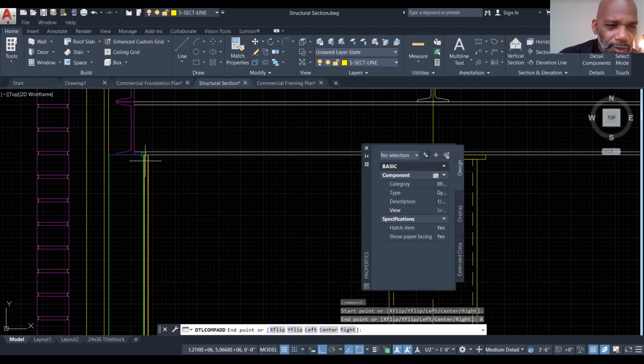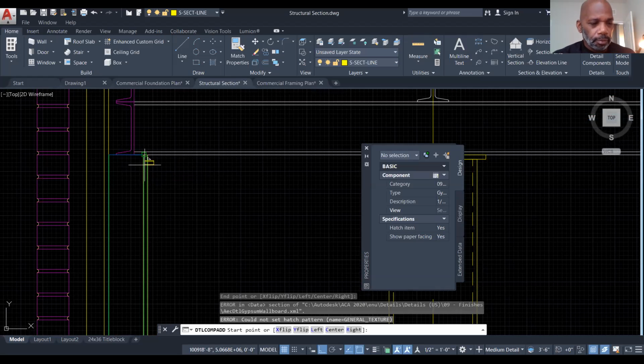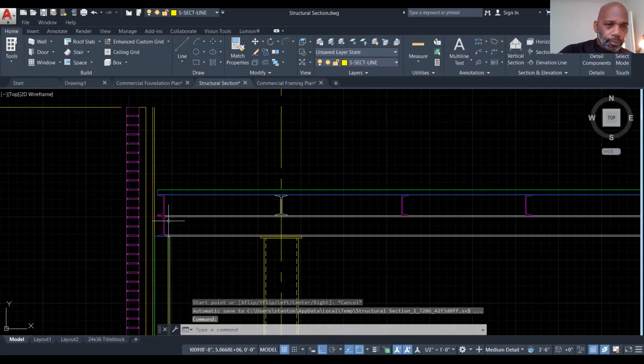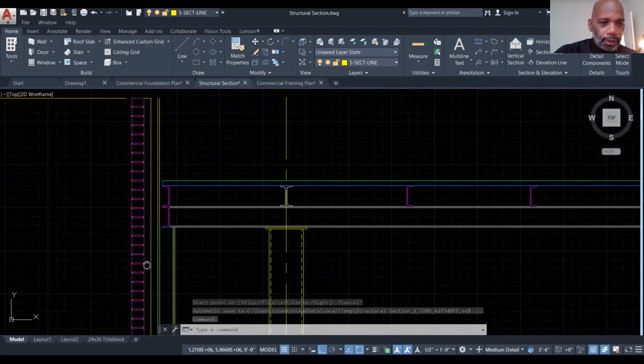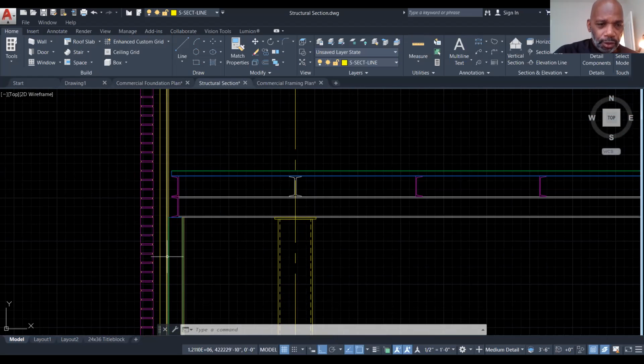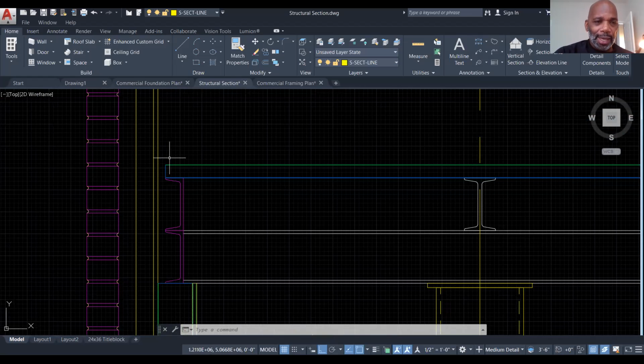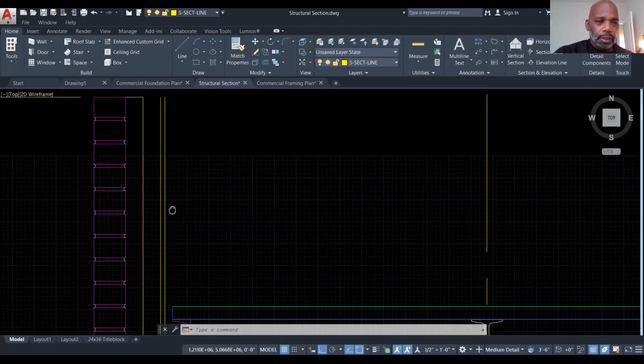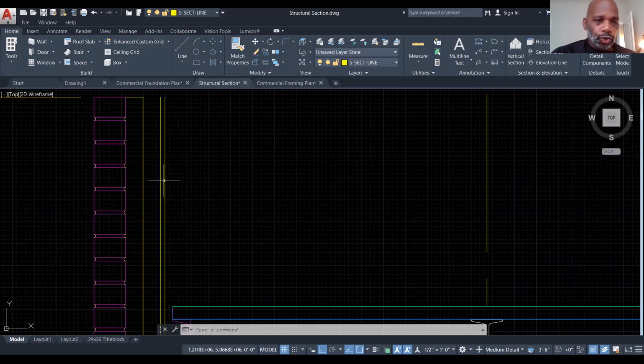Okay, so this comes up to the underside of the steel beam here. Good. So now airspace, insulation, gypsum sheathing, 4-inch metal stud, 16 inches on center, interior gypboard. All right, so now I'm going to come up here and we're going to add the metal stud again, a metal stud to support this portion of the gypsum sheathing above the roof.